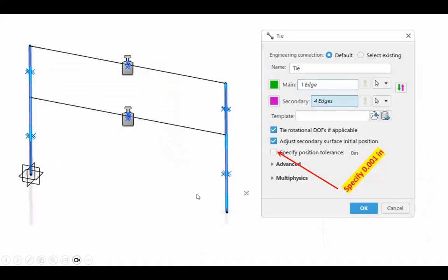And now we're going to be defining, you'll see that we're going to declare this top floor and the bottom floor as rigid entities, and rigid entities have a reference point, and we place the mass of the top and the bottom floors in that location, that reference point.